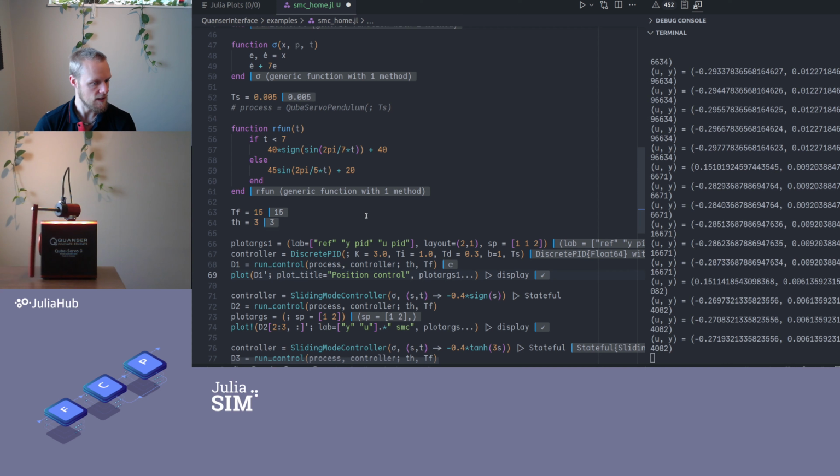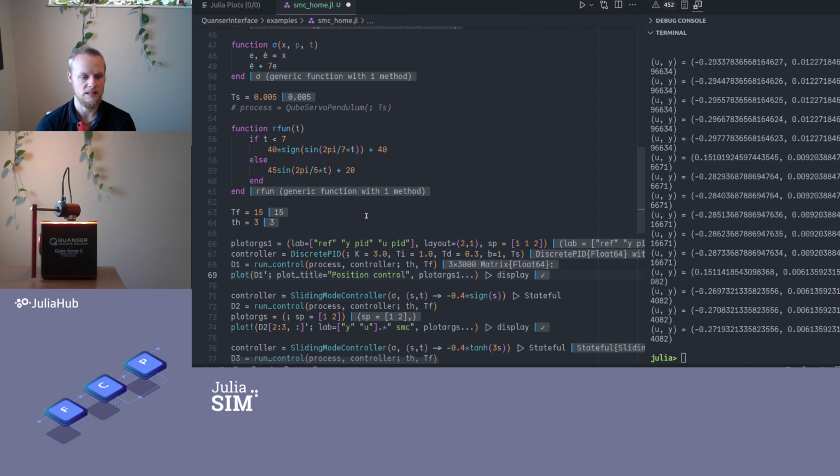But this kind of simulates how control design takes place on the factory floor, out in the field, where you don't have a very accurate model of the system. You're just tuning the gains slightly, and the PID controller is very often used for that.